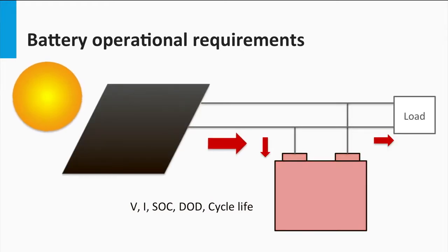You have also seen previously how a lead-acid battery responds poorly to overcharge and overdischarge. You also know how the PV array responds dynamically to ambient conditions like irradiance, temperature, and other factors like shading. Under such circumstances, a direct coupling between a PV array, battery, and load is far from healthy for the battery.